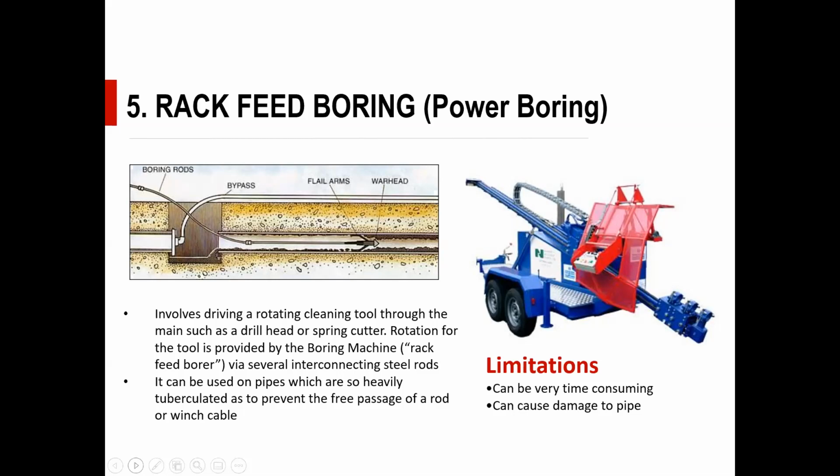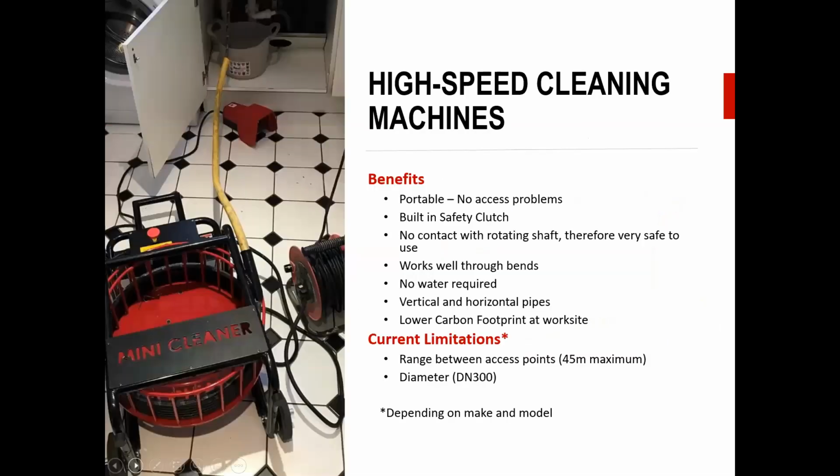It can be time consuming. I've been on job sites doing pipe rehabilitation on a water main where I've been on site 2 or 3 days while they clean the water main, and then the lining system is very quick. But the cleaning side can be very time consuming, certainly for rack boring, drag scraping and pigging. So they're the traditional methods.